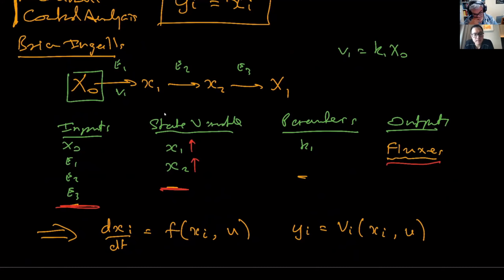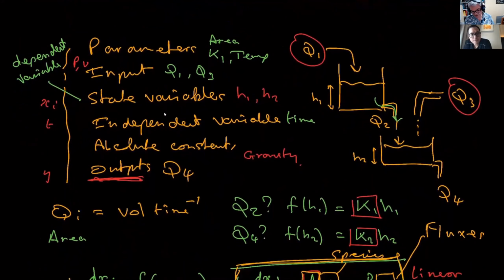So, any questions, or is that it then? As in state variables, do you also estimate parameters in real experiments? In real experiments? Yeah, because in models, you generally... Oh yeah, these things are generally unknown, right? We might not know the diameter of the output pipe. Maybe we don't know the diameter of the tank because it's hidden behind a wall, and all we see is a little strip that tells us the height.